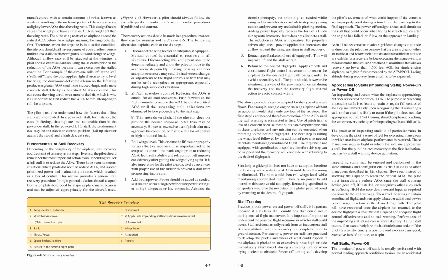Performance of the impending stall maneuver is unsatisfactory if a full stall occurs, if an excessively low pitch attitude is attained, or if the pilot fails to take timely action to avoid excessive airspeed, excessive loss of altitude, or a spin. Full stalls, power off.